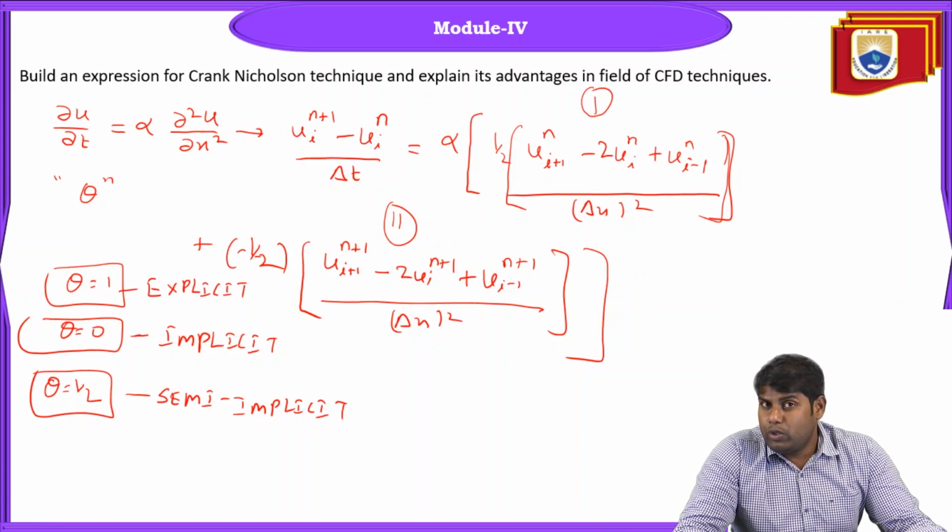When you make changes either in the time step or the space changes in the grid, the simulation adjusts automatically and will go on smoothly. Now for the explicit method, when you change the time step, it will be conditionally stable. For the implicit method, whether you change delta t or delta x, it is unconditionally stable. There won't be any conditions for the stability. So implicit methods are basically unconditionally stable.